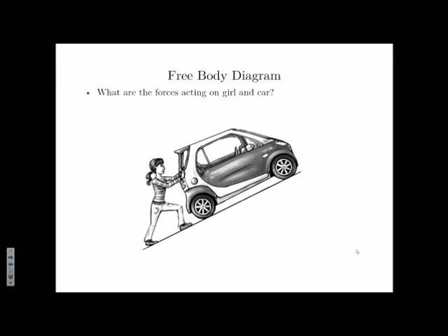Another assumption that we make in engineering is the assumption of a physical object idealized as a particle or as a rigid body. So what's the difference? A particle in engineering is not a mathematical particle. We deal with what are known as engineering particles. Engineering particles have mass, but they have no size or shape or volume. So we can idealize physical objects as point objects, as points. You will just show them as a point, but they have mass. And it's an engineering particle. It's not a mathematical particle. Mathematical particles are just points. They don't have any mass.